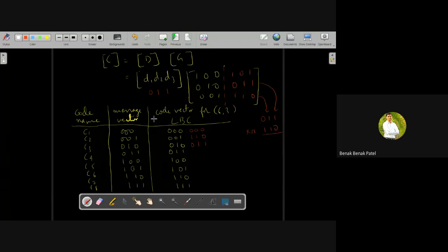So how exactly does an XOR gate work? I can do this XOR, or it's also called a modulo 2 operation, mod 2 addition, such that for similar inputs I'll get 0 as my output, and for different inputs I'll get 1 as my output. So this goes over here, 101.